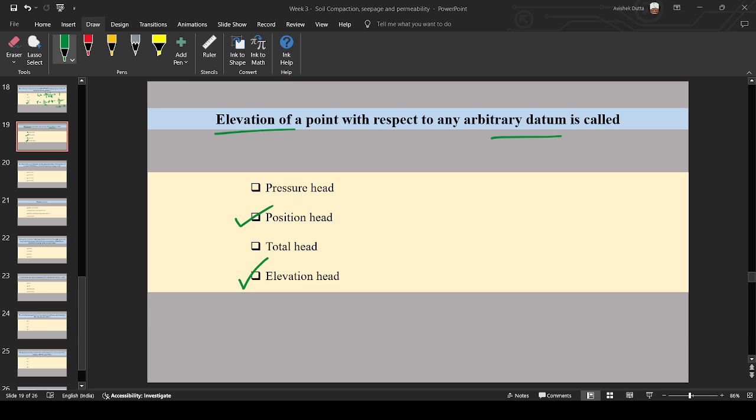Okay, this is easy. The critical hydraulic gradient, IC, the formula is G minus 1 divided by 1 plus E. So G is 2.67, 2.67 minus 1 is 1.67, and E is 0.67, 1 plus 0.67 is 1.67. The value of I becomes 1. So this is the formula you have to remember for solving these questions. Very important. IC equals G minus 1 by 1 plus E.